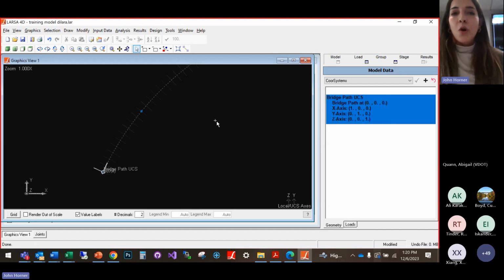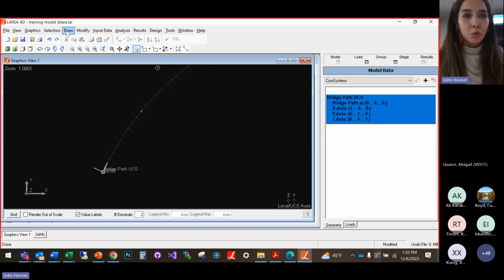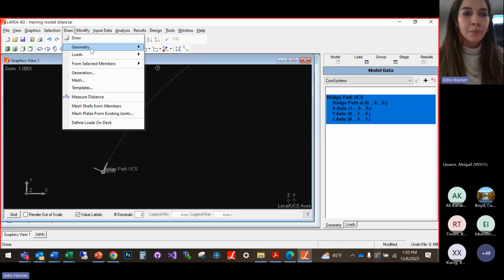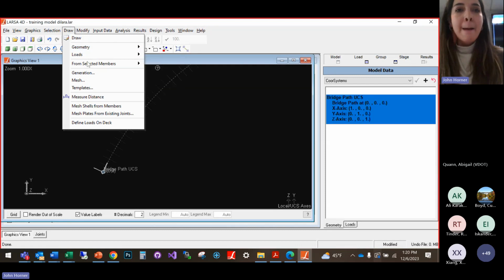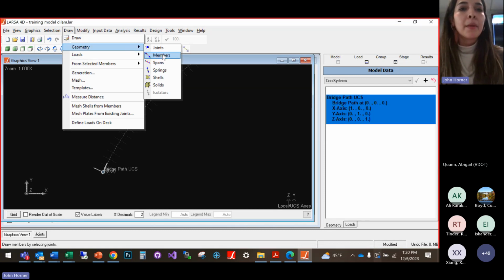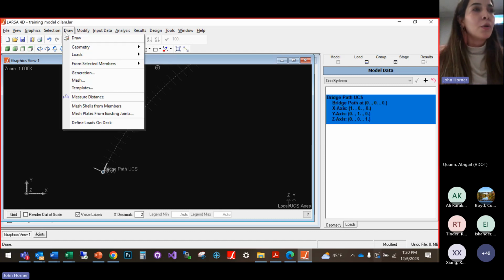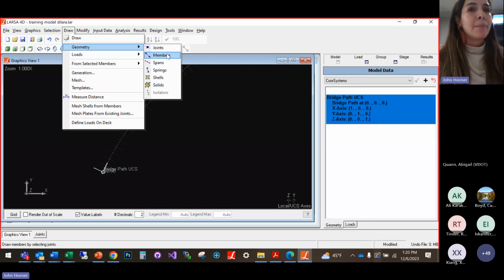Okay, to draw members, I will get the draw tool by going to input data, draw, geometry, members.